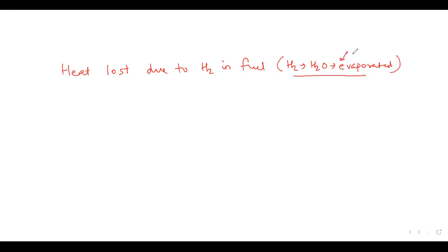Heat lost due to hydrogen in the fuel. What happens to this hydrogen? This hydrogen is getting converted to water vapor, which is evaporated, and this is a loss because the process requires energy. So this energy is a loss.